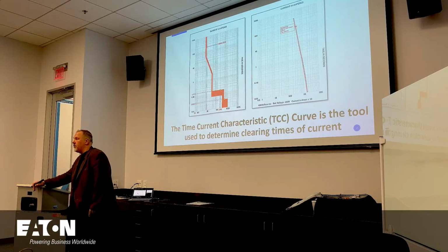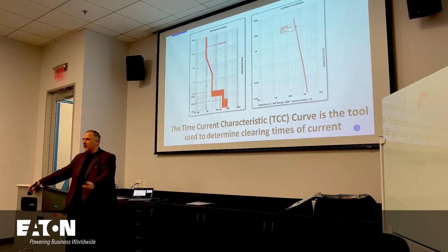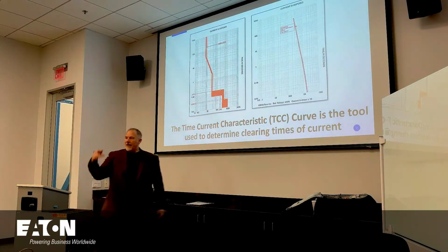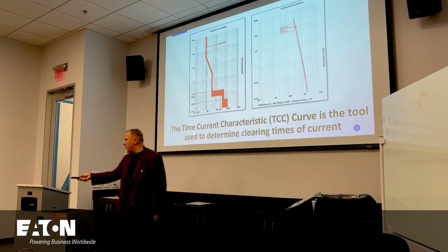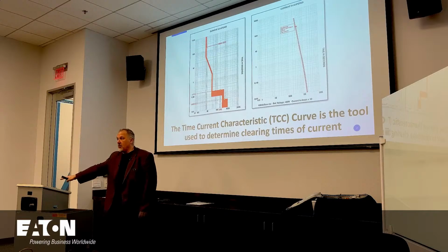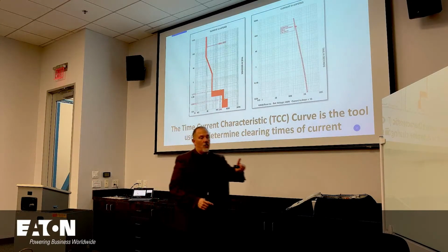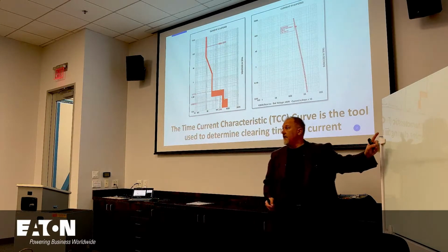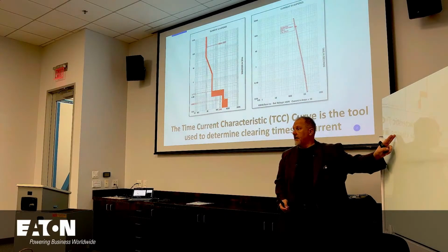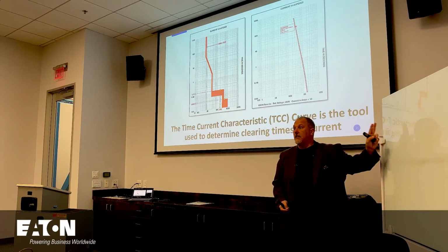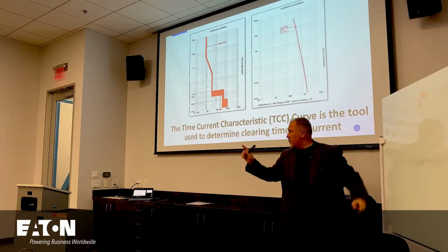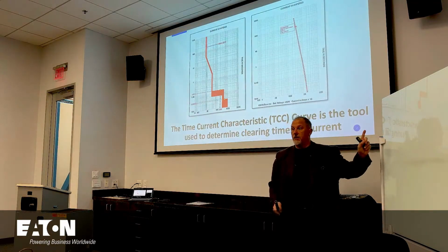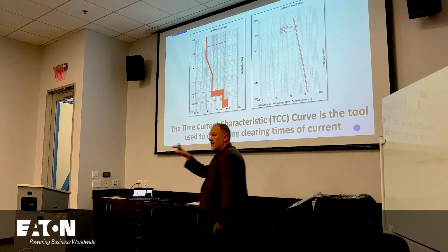So if this is a panel board and I turn off the main, I can do all that jazz. I still have incident energy, I have potential here, but it's based upon whatever breaker is feeding it from the upstream overcurrent device. And I call that the protecting device, because this device, which feeds that piece of equipment, is what's going to determine the incident energy here.